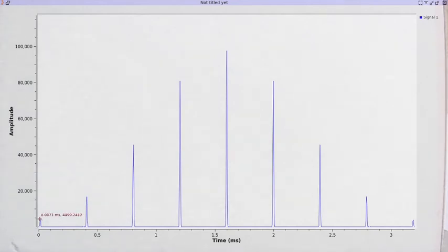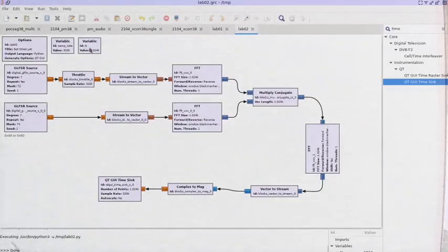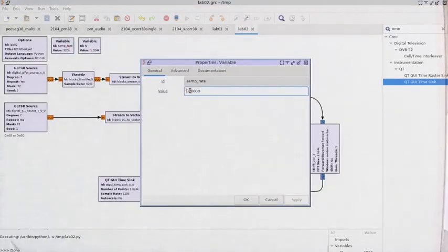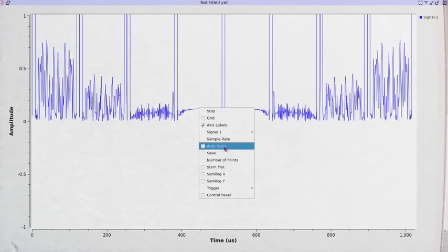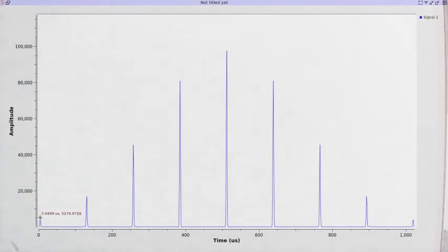at offset. Well, that's not very convenient because the millisecond is a time that is not an integer, so let's make it in microseconds, and that will make it easier to read. If we now autoscale with the middle button, we see that the first one is at 3 microseconds, but the second is at 130, so that's indeed 127 taps long, so that's the number of elements.